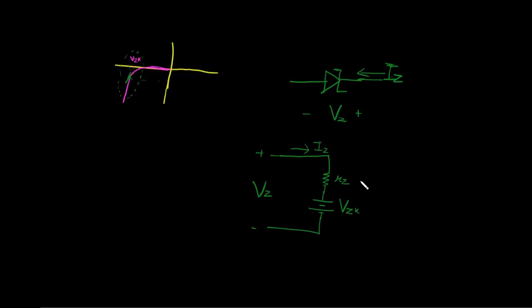So a Zener diode should not be operated in the low current region, it should always be operated in the higher current region, as the magnitude of this slope is very large for low currents. So RZ has a high value for low currents. So it is advisable to operate this diode in the high current regions. We will later see the practical use of Zener diodes in solving problems, how much the current or voltage will be in the circuits, and the power dissipations, etc.